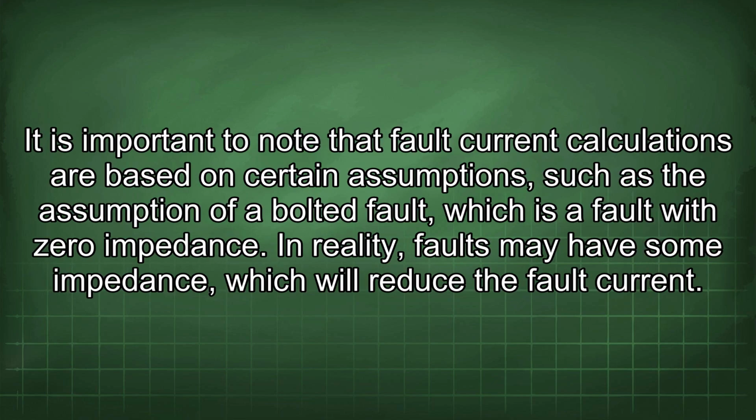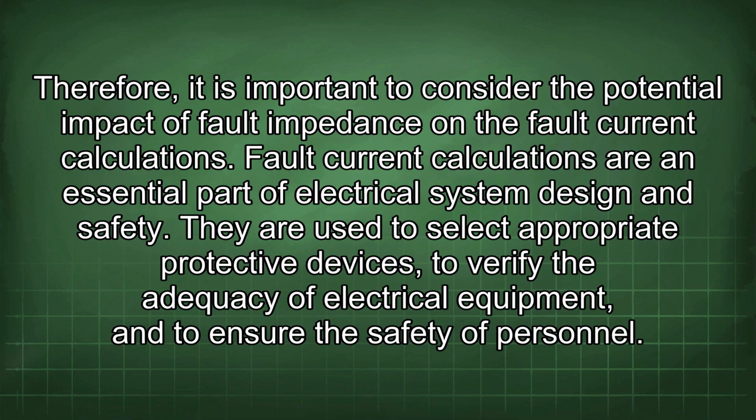It is important to note that fault current calculations are based on certain assumptions, such as the assumption of a bolted fault, which is a fault with zero impedance. In reality, faults may have some impedance, which will reduce the fault current. Therefore, it is important to consider the potential impact of fault impedance on the fault current calculations.